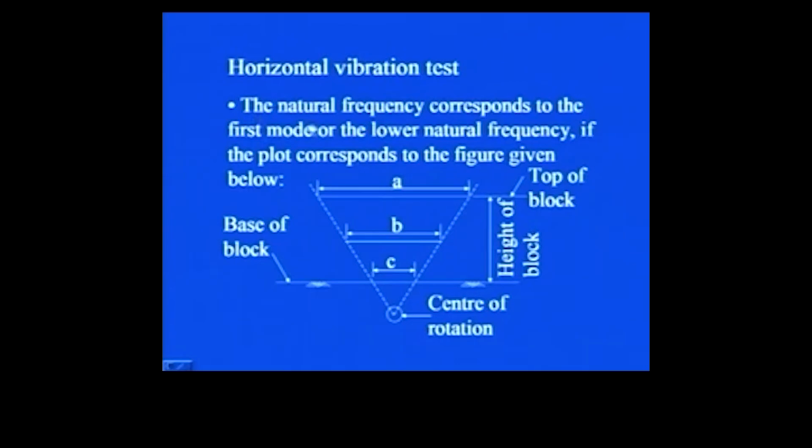Now, the natural frequency corresponds to the first mode, or the lower natural frequency, if the plot corresponds to the figure given below. If I am plotting with respect to the height of the block, this is the response, this is the center of rotation, this is the top of the block, and this is the base of the block, where it is in contact with the soil. If the amplitude keeps increasing in this particular case, the natural frequency corresponds to the first mode or the lower natural frequency.